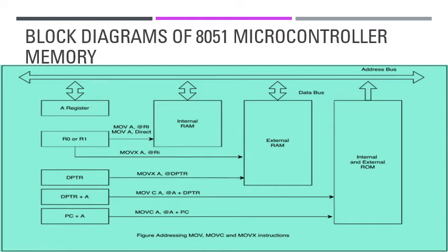The basic difference between a microprocessor and microcontroller is the on-chip memory. A microcontroller consists of an on-chip RAM, that is data memory, and ROM, a program memory. The program memory is used for permanent saving of code or program that is to be executed in the program counter, whereas data memory is used to temporarily store intermediate results and variables. For a CPU to process the information, it should be stored in either RAM or ROM. These are referred to as primary memory.